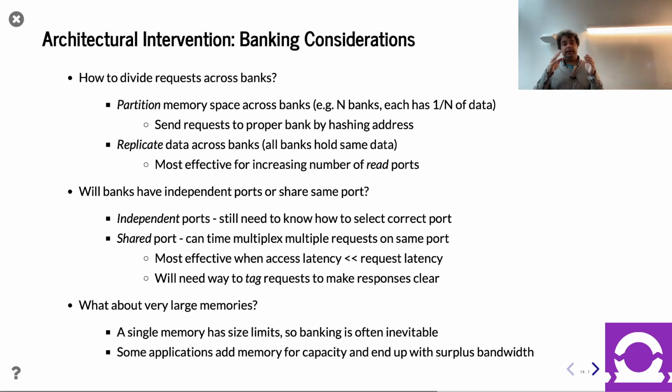Now, guess what? When it comes to memory, within Chisel, for example, if you have 2 ports in your memory, let's say one's a read port, one's a write port, and they're both going to the same address, does the read get the old data value or the new data value? That actually depends what technology you're using, right? Some FPGAs, the ASICs are different, right? So Chisel actually has a way, using more verbose arguments in the memory construct, you can tell it which behavior to have. So there's actually some ways to literally tell that in Chisel, but also when it comes architecturally, it's up to you to kind of make that enforced.